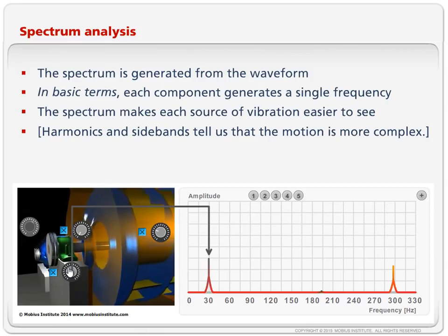It's understanding the failure modes to say, well, how quickly does the condition degrade? And I've got to make sure that I get at least 2 measurements in the time where it's going from healthy to the time where it is functionally failed, where we are being forced, either because it's catastrophically failed or it's just unable to perform its function. We want to take enough measurements to detect that. It's not so much to do with criticality. Criticality tells us whether we can justify doing it. The PF interval, or the time to failure, tells us how often we should do tests.